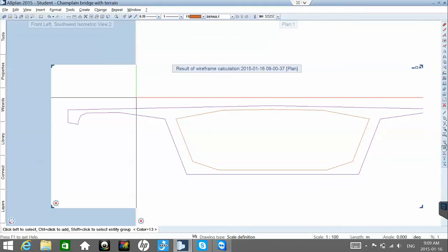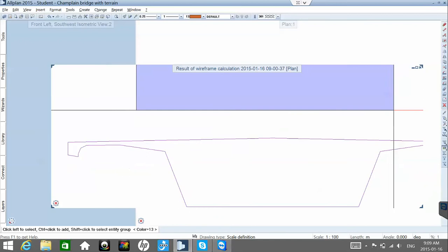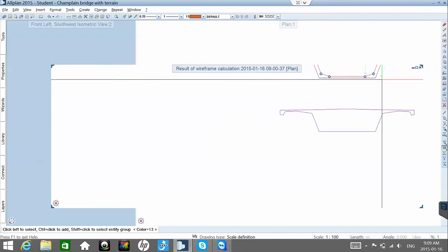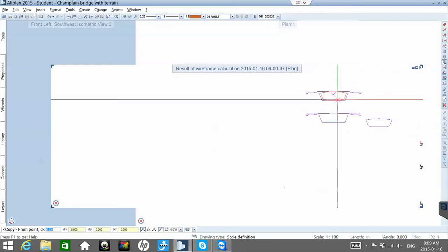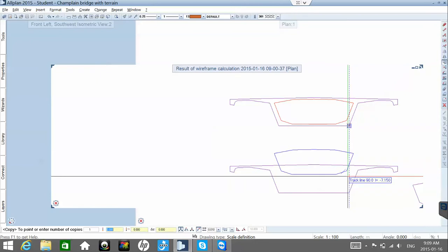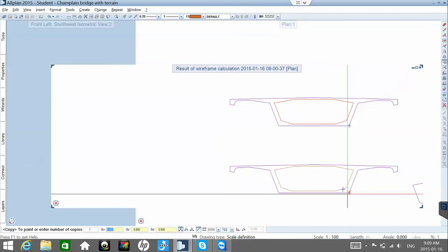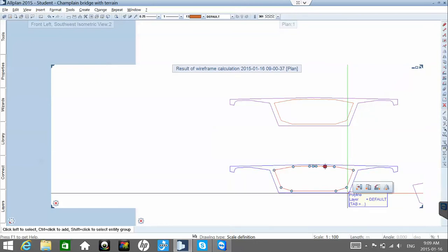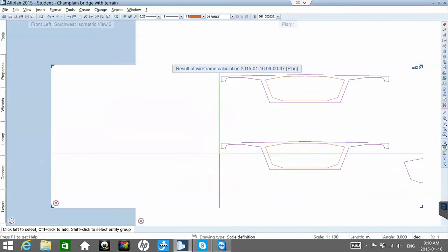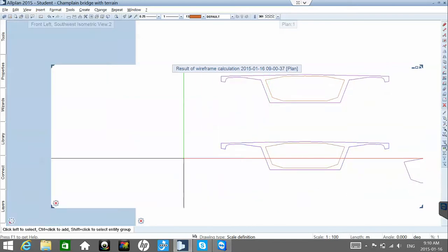So you just select this area. This is how we make sure we select only color 13. And now we should say copy. The reason I chose the section above is because I can pick this point and place it here, so I have the correspondence between the two cross sections. Now you do the rest, add this cross section. No, you finished. You just need to add this.